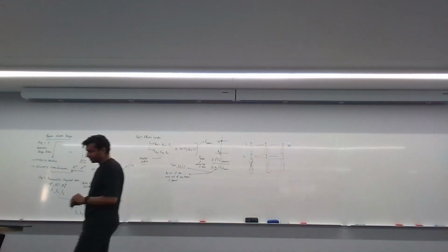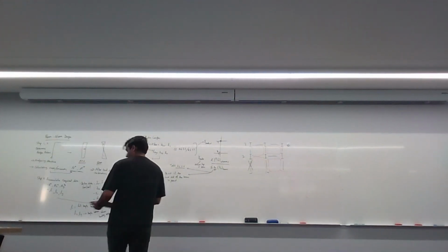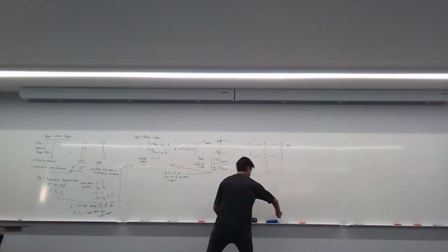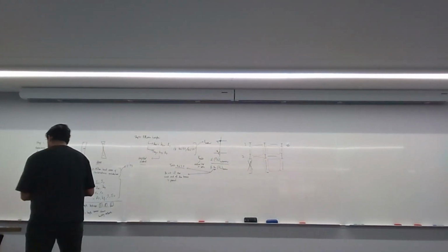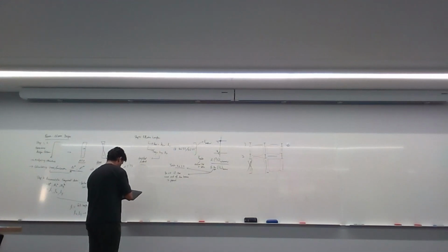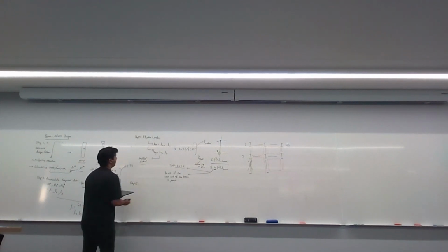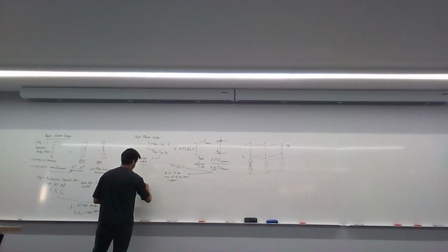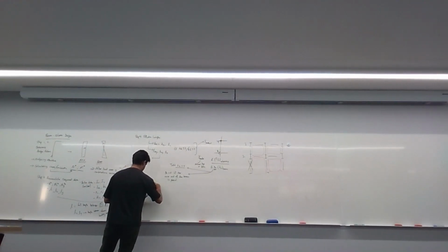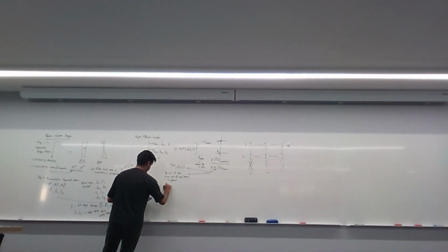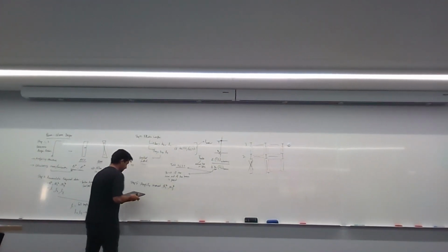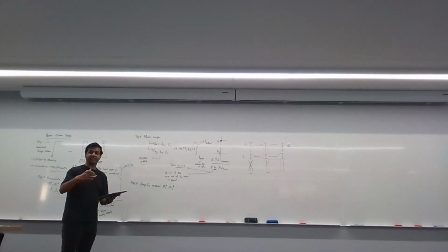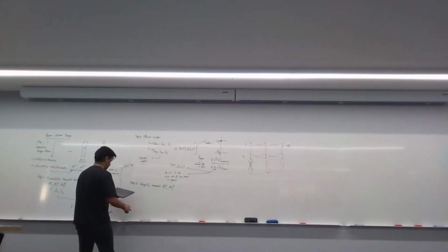Now the next part of this. Once we have gotten our effective length and completed the gamma method, the next step is we need to amplify our bending moments, Mx star and My star. Now remember, for braced or sway, we have 2 different types of moment amplification factors.